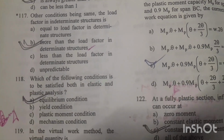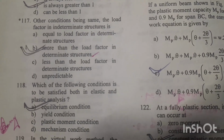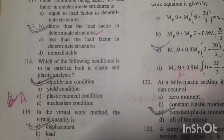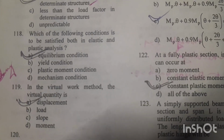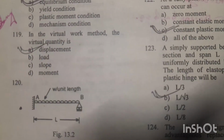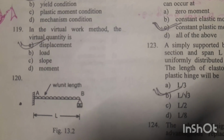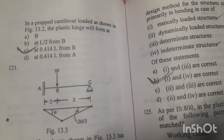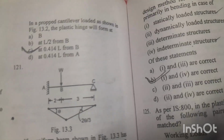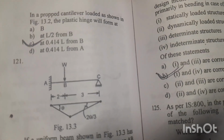Question number 118. Which of the following conditions is to be satisfied both in elastic and plastic analysis? Equilibrium condition. Option A is right answer. Question number 119. In the virtual work method, the virtual quantity is displacement. Option A is right answer. Question number 120. Look at the propped cantilever beam of uniformly distributed load W per unit length. In a propped cantilever loaded as shown in the figure 13.2, the plastic hinges will form at a distance 0.414 L from B. Option C is right answer.